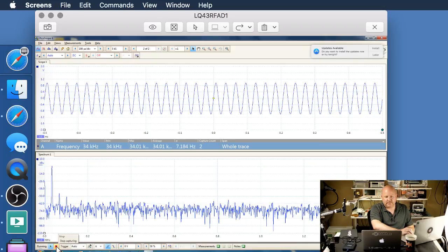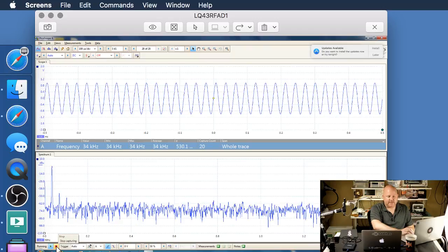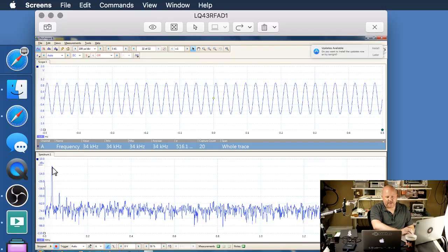Let it build up its buffer, and you should already notice a couple of things. First, we now have a spike down here, and it's at, this is showing 36 megahertz, probably just a resolution thing. But if you notice, back out here, we still have a spike around 1.5 megahertz. My guess is that on this unit, the arbitrary waveform generation circuit, the AWG, has a 1.5 megahertz clock driving its digital to analog converter, and that's why we could see that spike. All right, I wanted to show that real quick.